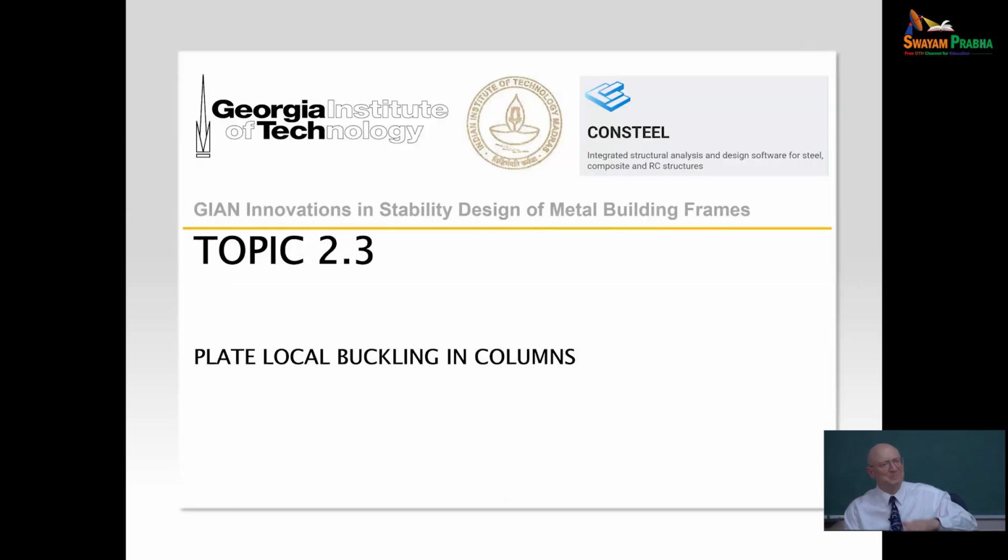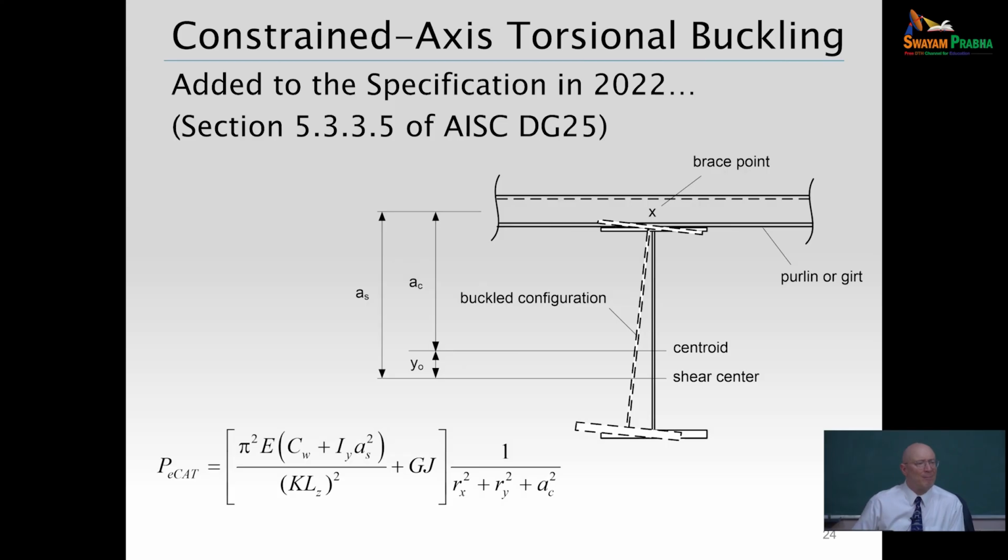In some metal building structures, we see these braces going from the bottom flange, the inside flange, to the girts or purlins. That's the flange diagonal bracing. The intent there is to also provide lateral bracing to that inside flange.